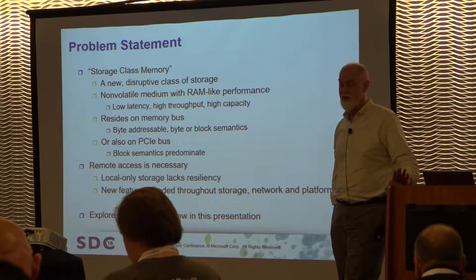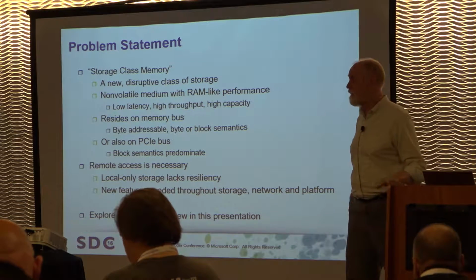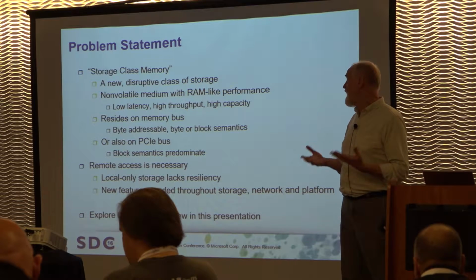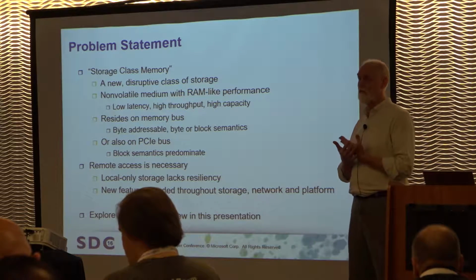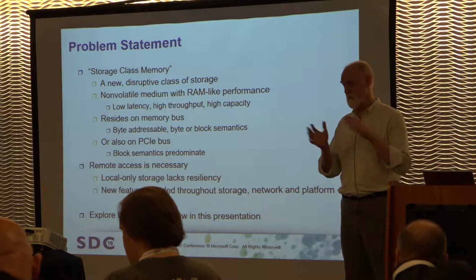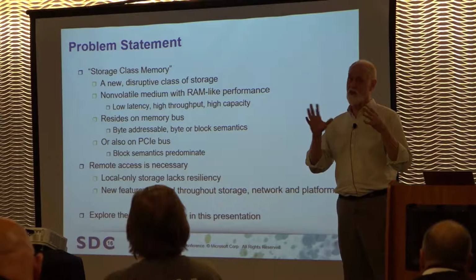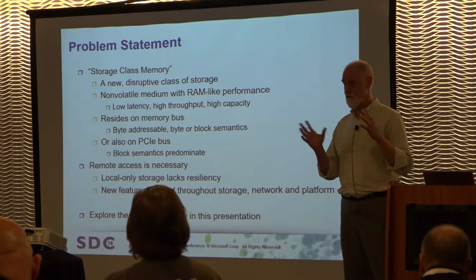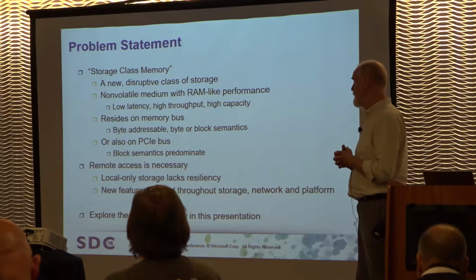It has low latency. It has high throughput. It has good density, high capacity, all right? It resides on the memory bus. Therefore, it's byte addressable. It has byte semantics. You can read and write a single byte, or maybe a cache line, but something really small. It also has block semantics when you layer a driver on top of it, and that's how Windows deploys it. There's sort of two personalities to this type of device in Windows.